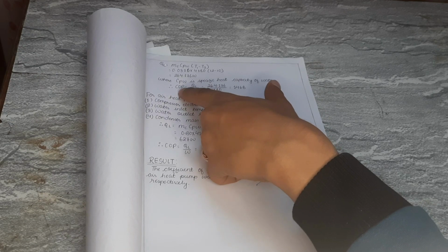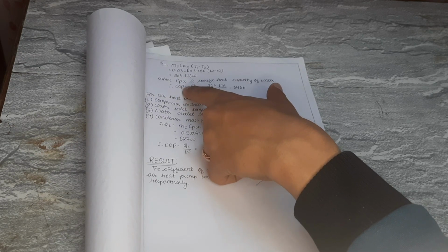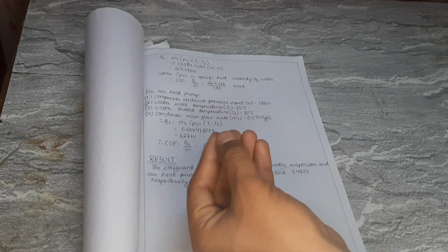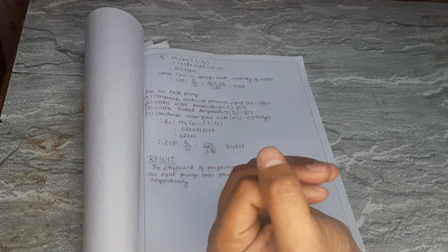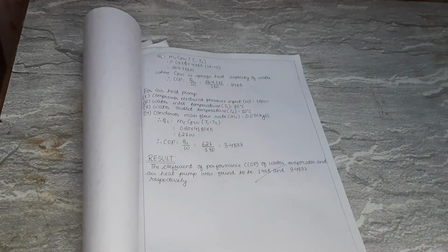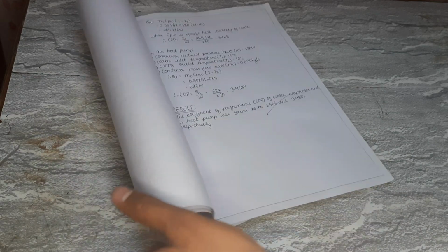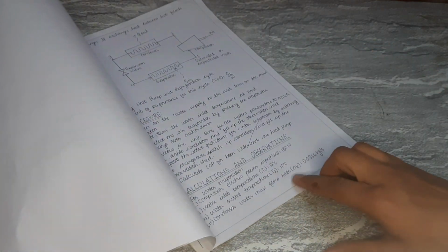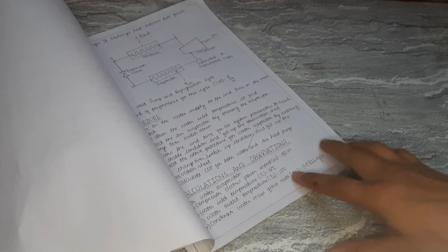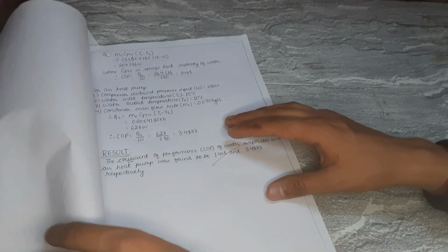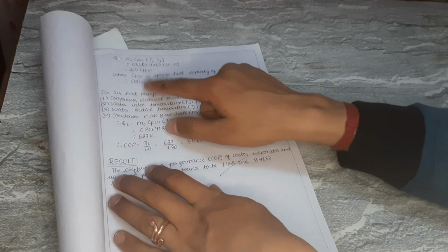We also need to determine the COP, also known as coefficient of performance, right? That is QL, the heat supplied at the lower temperature, divided by total work done. We have calculated that from earlier. The work is 180 watts, given directly by the supply electric power, and in this way we can calculate the value of COP.